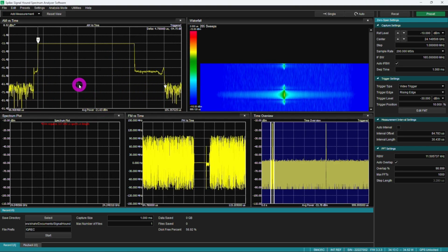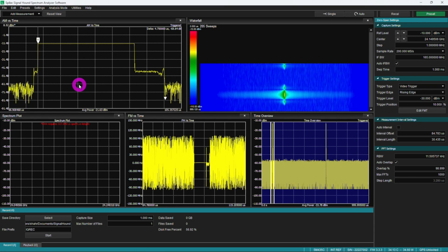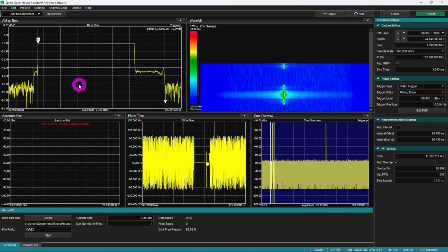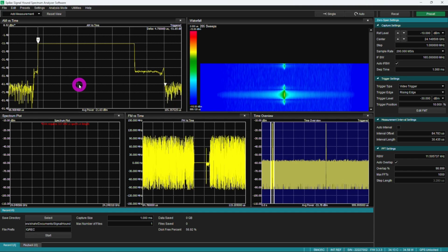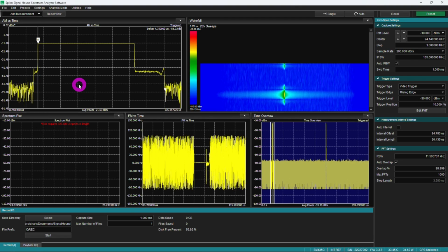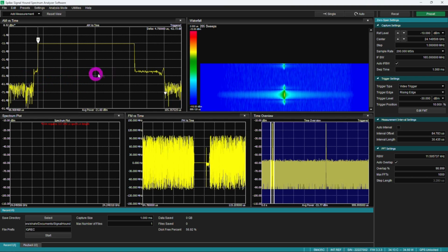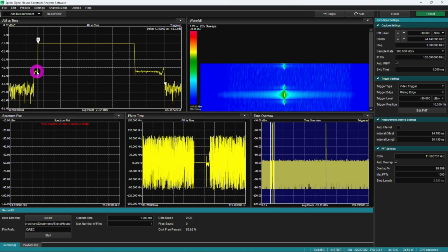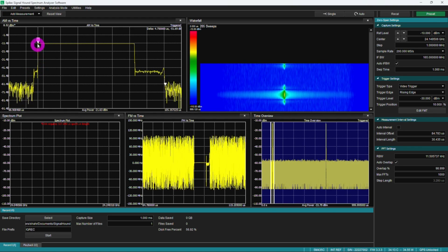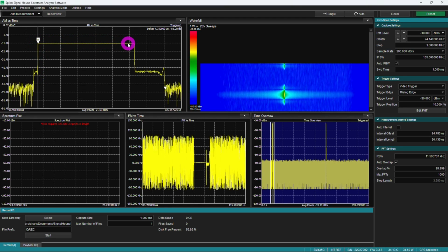So let's think about what a radar like this wants to do. This wants to be as low power as possible, so it doesn't want to do anything when there are no pulses. And I think what happens internally is that it turns the VCO on, the VCO stabilizes, and then it turns on the power amplifiers to their maximum gain, transmits the pulse, turns the PAs off, and then goes ahead and turns the VCO off. It does it in multiple stages, and you can clearly see that characteristic here in the pulse shape. You can see we are putting out a little bit of power, and then the power jumps significantly. Remember, the delta between these two is huge. We're talking about tens of dBs here. And then it's flat across the entire pulse, which is good.